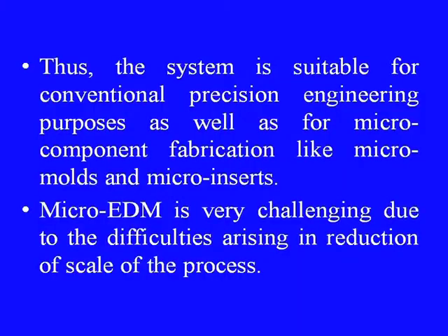This process also has a servo system with high sensitivity and positional accuracy, which is something near plus or minus 0.5 micrometer. This permits the setting of a minimized discharge gap of 1 micron. Thus, the system is suitable for conventional precision engineering purposes as well as for micro component fabrication, like micro molds and micro inserts.